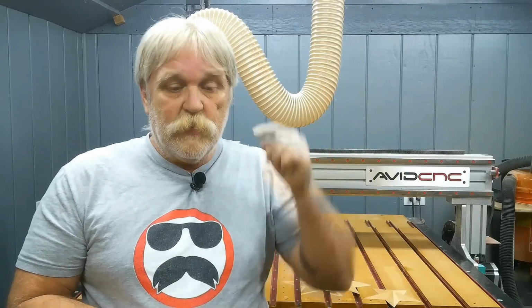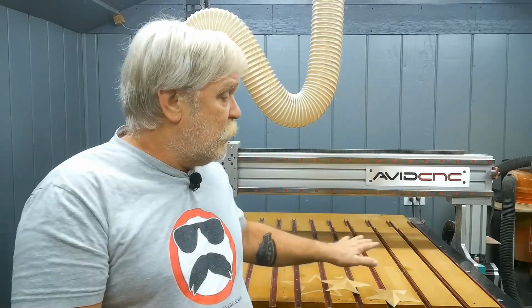If you're drilling a hole, for example, and it's important that that hole be a specific depth below the surface of that material, then setting your Z0 to that material surface is the appropriate place. Now, if you're drilling all the way through the material and don't want to go way into your spoil board, then the machine bed would be the appropriate place to set your Z0 position. Generally speaking, if you're V-carving or pocketing to a specific depth from the material surface, then the material surface should be where you set your Z0 position.